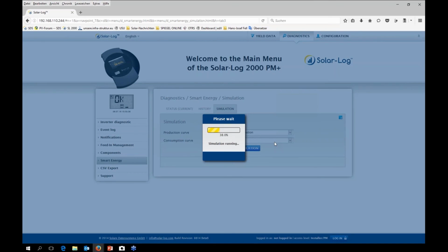With this configuration, you can also do some peak shaving. For example, if the consumption is higher than 10 kilowatt, turn on the CHP. Then you have an additional generator for your self-consumption, and you don't need to take such high loads from the grid. This can save a lot of money in a lot of installations if you do peak shaving. Load peak shaving, not production peak shaving.